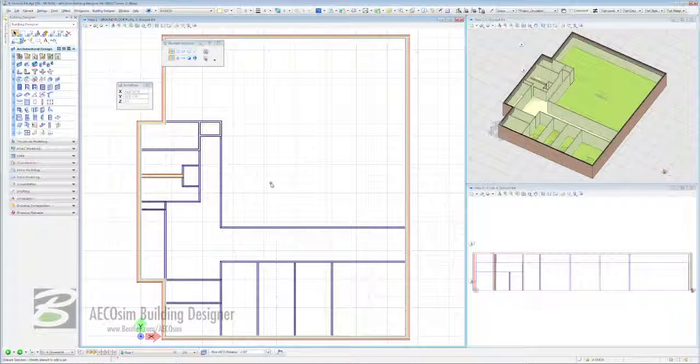This is almost how it looks. In fact, it is how it's going to look when you place it on a sheet. You have the hatching of your materials. You have the outlines, we have the grid there that's been slightly faded into the background, but is there to guide us. And what we're going to do now is utilize these different ways of looking at things to place our doors. So to begin with, we're going to go across to our task-based interface to Architectural Design, 5 down, first icon in, Place Door.